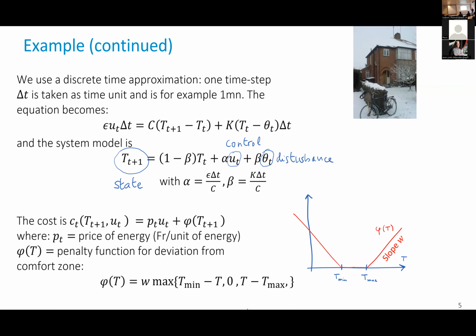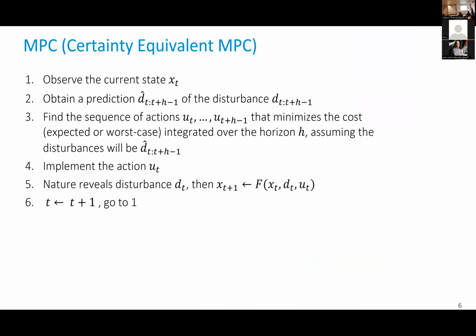So it's not like a hard constraint that we have, for example, when we have a generator that has a maximum speed. If it goes above a certain speed, you might have damage. Here, it's not the case. So it's really acceptable to have a soft constraint. But typically, we will take a penalty, the price of the penalty here, that will be very large to make sure that de facto, it acts as if we had a hard constraint. That's the standard technique. So this is how the model is posed, but now back to MPC, which is the heart of the topic today.